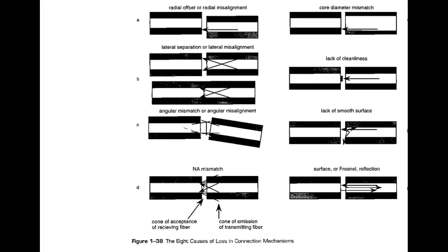So the cables themselves look the same. The cladding is 125. Our cladding is 125. But if I had our 62.5 on this side, and over here we had 50/125, they look exactly the same because the cladding is 125 microns on both of them.